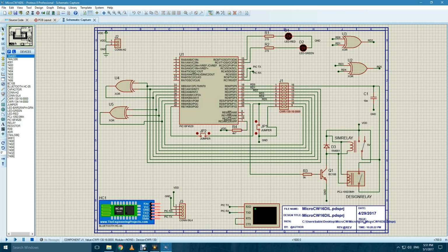when we're checking DIL 16 devices, pin 7 actually has to be connected to an input in the controller, and pin 8 has to be connected to the ground. If the hardware is supposed to support both of those designs, we had to add 2 small jumpers. Alternatively, somebody can use a switch. When we are testing DIL 14 devices, the jumper connects pin 7 to the ground as it should be, and JP2 should be open, therefore isolating pin 7 from the input of the controller.